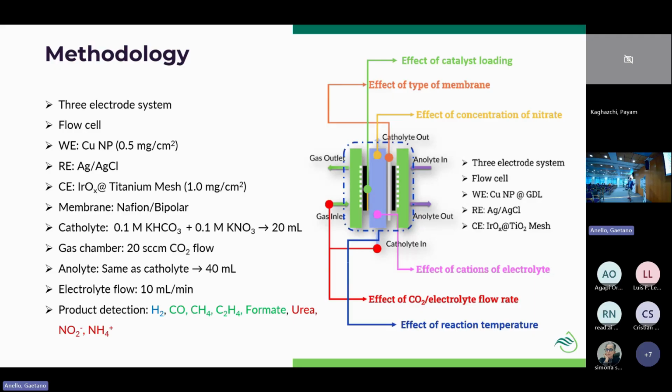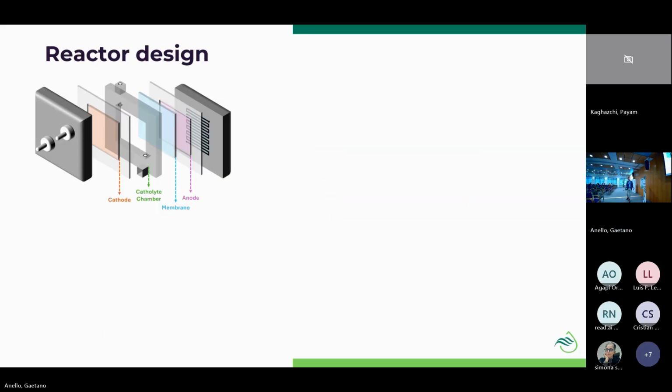And we specifically have a look at the effect of all the parameters in these electrolyzers, how they affect urea production. So here again is an overview of the electrolyzer. Here you see the electrodes, the cathode, the anode, and this gap. This is a thin electrolyte gap, 3 millimeters thick. This side is zero gap.